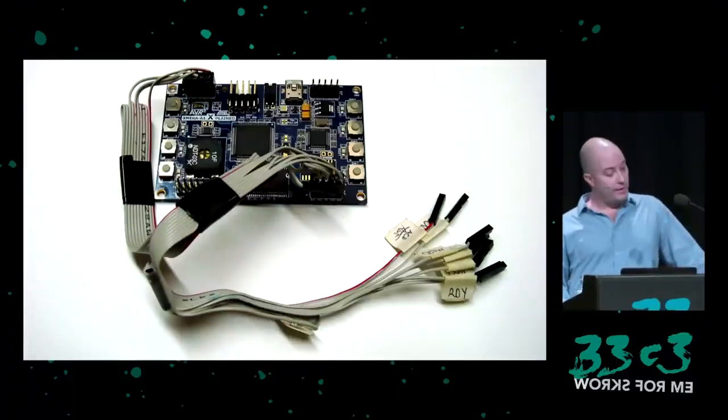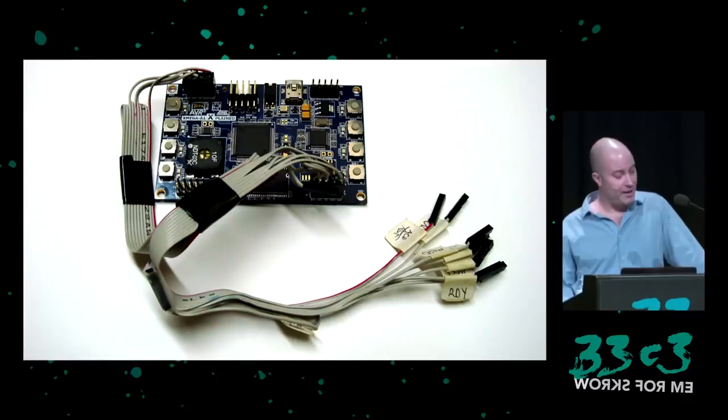At one point, I had written software for an AVR32 device, not the one that's shown here, that has a synchronous serial peripheral that supports sending and receiving data at the 27 megabit rate of the transport stream. My AVR32 implementation turned out a bit ugly. But rather than cleaning it up, I was able to use it as it was.